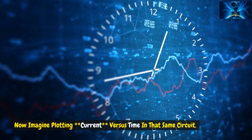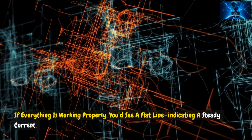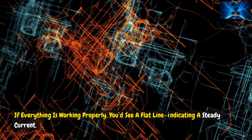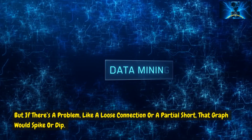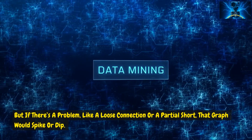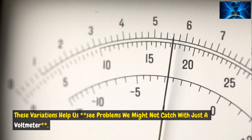Now imagine plotting current versus time in that same circuit. If everything is working properly, you'd see a flat line, indicating a steady current. But if there's a problem, like a loose connection or a partial short, that graph would spike or dip. These variations help us see problems we might not catch with just a voltmeter.